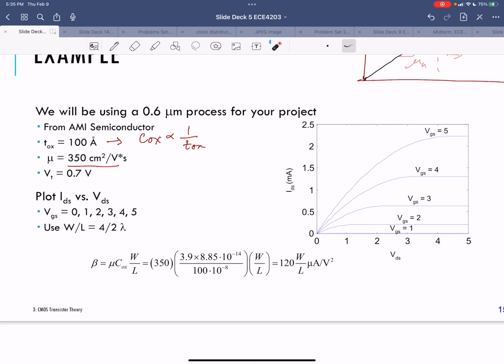And then you basically end up with plots of IDS versus VDS, like the plots I mentioned. Just to again point out these dependencies, you notice that as VGS is below 700 millivolts, all those curves are basically lying on top of each other at IDS equal to 0.